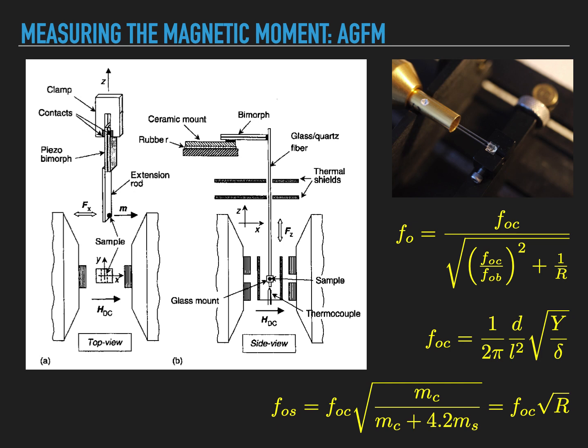This movement is in fact caused by a force that is converted by the piezoelectric transducer into a voltage. If you drive the coils in such a way that the gradient is not constant over time but will oscillate over time, an alternating gradient field, then also the force at which your sample is submitted will depend over time.